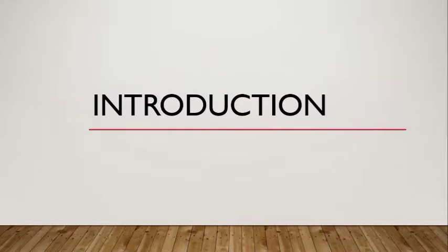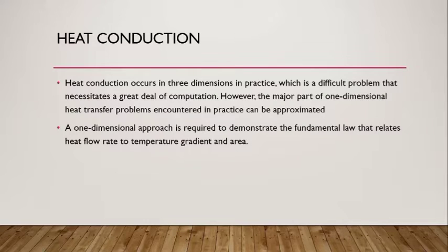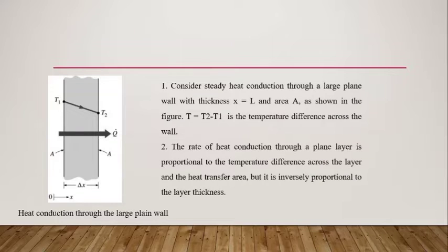Next, the introduction. First, about heat conduction. Heat conduction occurs in three dimensions in practice, which is a difficult problem that necessitates a great deal of computation. However, the major part of heat transfer problems encountered in practice are one-dimensional and can be approached immediately. A one-dimensional approach is required to demonstrate the fundamental law that relates heat flow rate, temperature gradient, and also the area. Here the picture shows heat conduction through a large plane wall.